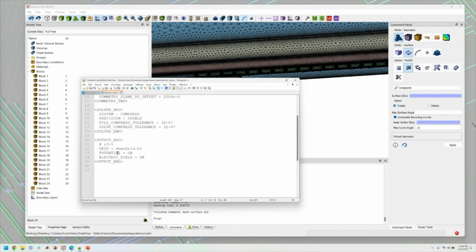I'm not going to cover any of that in the context of this discussion. All I point out here is that a nice convenient thing is that I can insert comments into the input decks. And in this case, I'm giving my codes downstream an instruction about which electrode to treat as the RF electrode in doing the subsequent sampling.